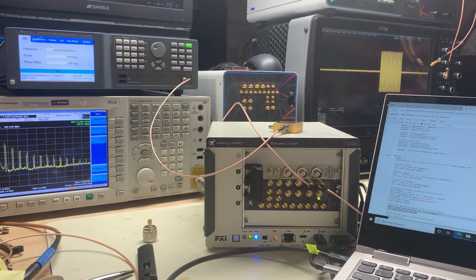So the carrier closest to the left hand side is the fundamental, and then you can see plus and minus 70 megahertz or 75 megahertz signals at multiples of the clock, so 1 gigahertz, 2 gigahertz, 3 gigahertz, 4 gigahertz, 5 gigahertz, 6 gigahertz, etc., all the way up to about 12 gigs. And we can use all of them when we're trying to generate different signals at different frequencies.